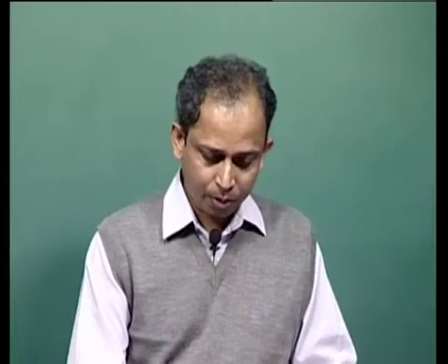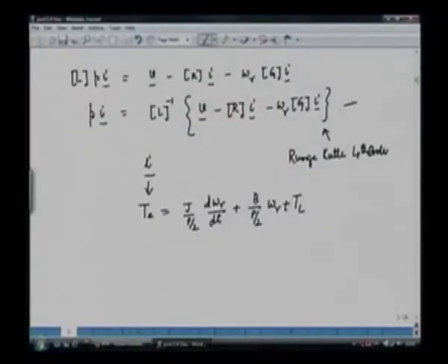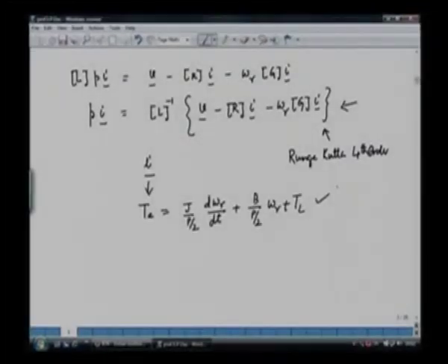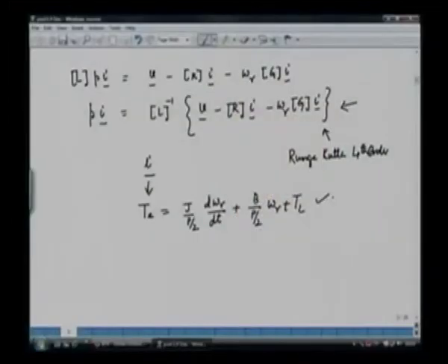What we are trying to do here is this, that the 4 equations that we have are IDS, IQS, IDR and IQR. We can solve them simultaneously by using Runge-Kutta 4th order technique. And then when we come to the speed equation, we have the mechanical variable and that varies much slower than the electrical variable. So while simulating the electrical variable, we can assume omega r to be constant.